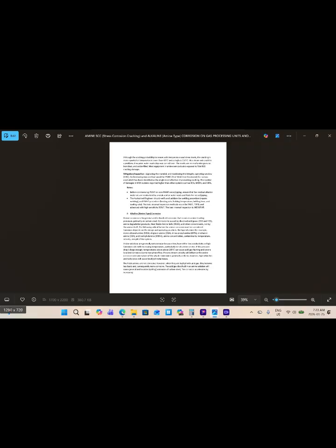Process stream velocities influence the amine corrosion rate and the nature of the attack. Corrosion is generally uniform; however, high velocity and turbulence will cause localized metal loss.